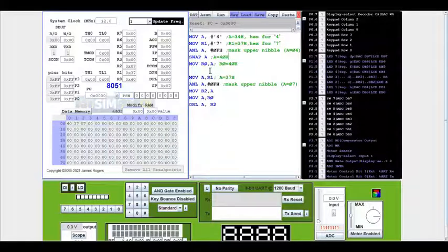So now you have 40 in R0 and 7 in R2. Okay. So next, if you OR the 40 and 7, then you'll get 47. For that, I need to get the R0 value into the accumulator, because for the OR operation also the destination should be the accumulator. So I'm ORing 40 and 7 to make it 47. So we'll do this step by step and see.